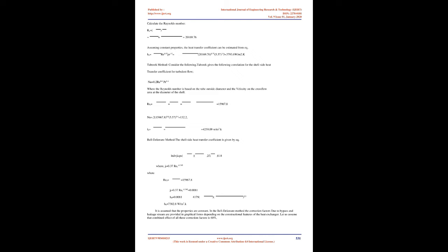Third, the exchanger must be maintainable, which usually implies choosing a configuration that permits cleaning tube side, as may be indicated, and replacement of tubes and any other components that may be especially vulnerable to corrosion, erosion, or vibration. This requirement may also place limitations on positioning the exchanger and in providing clear space around it. Fourth, the exchanger should cost as little as is consistent with the above requirements. In the present context, this refers to first cost or installed cost, since operating cost or cost of lost production due to exchanger unavailability have already been considered by implication in the earlier and more important criteria.